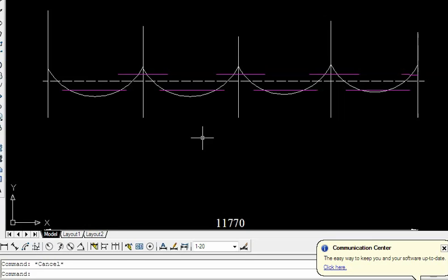That's why at positive the reinforcement will be higher than the distribution provided at the midspan. So here you can see midspan the spacing will be 8 at 100, while at the support it will be 8 at 300, because the moment at the edges is less compared to the midspan. So at midspan the spacing will be less, and at the support it will be more.